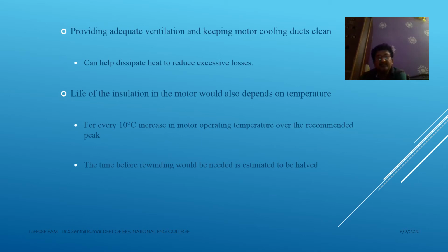So this can dissipate the heat, and it reduces the excessive losses in the motor. And the life of the insulation of the motor will depend on the temperature only. So if we clean the motor frequently, maintaining the ventilation, providing adequate ventilation to the motor, surely the temperature of the motor is not going to rise. How much temperature is generated is how much temperature is dissipated to the environment. Then the life of the insulation of the motor is protected.